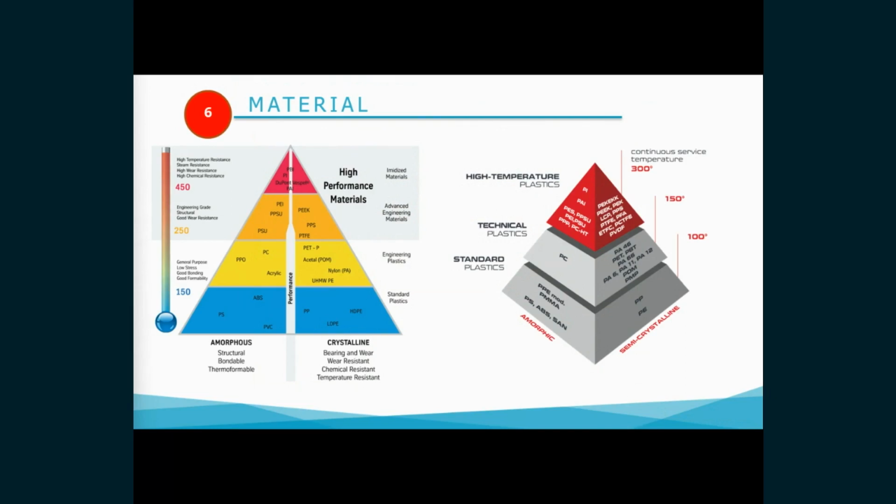Acrylonitrile butadiene styrene (ABS) is valued for its strength, durability, robustness, and temperature resistance. It is good for making conceptual and functional models. It is printable at about 220 degrees Celsius with a heated print bed.